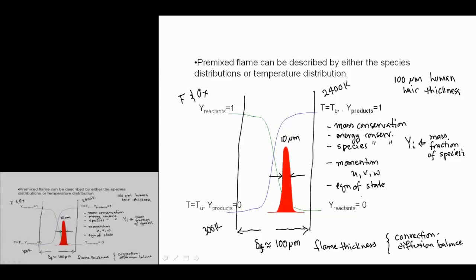This is one differential equation. Energy conservation is at least one, and if we couple it with radiation, then we have to solve the radiative transfer equation. Depending on the number of species that we're tracking, we could be tracking 200, 300, again, 1,000 species. Momentum, we're solving for U, V, W in a three-dimensional case, and then we have a constraint of this equation of state.